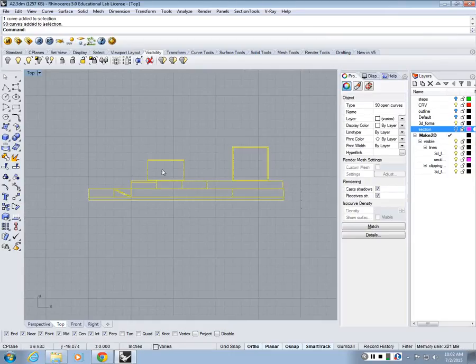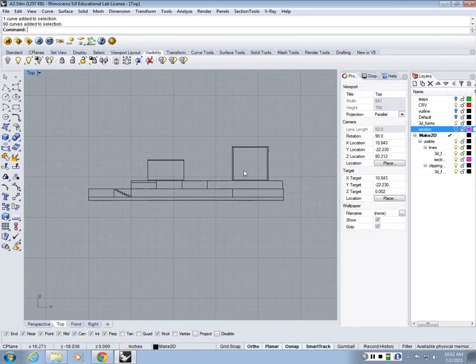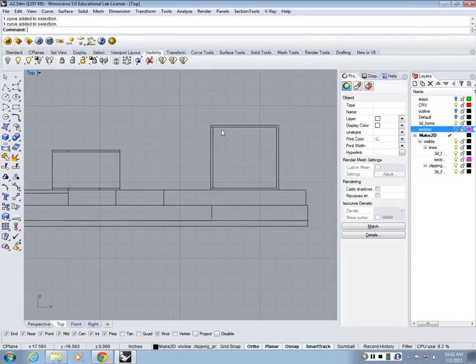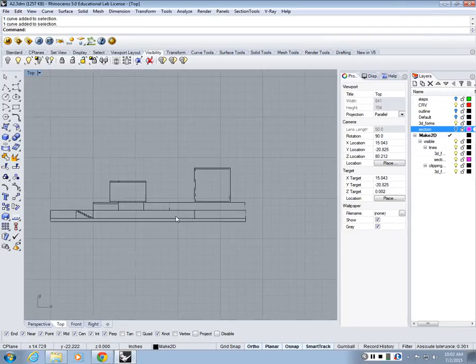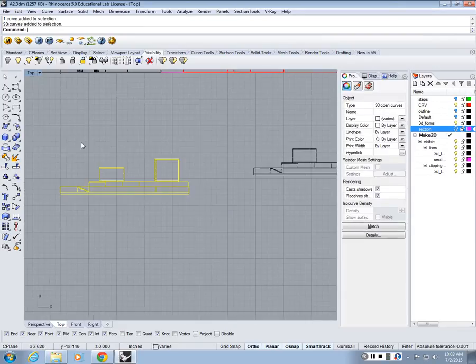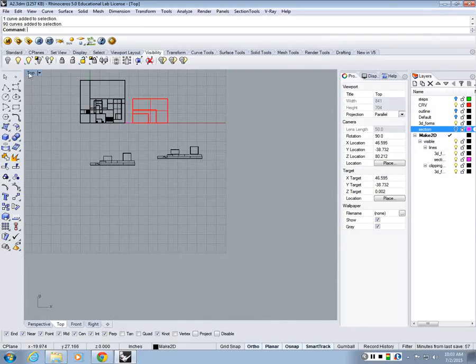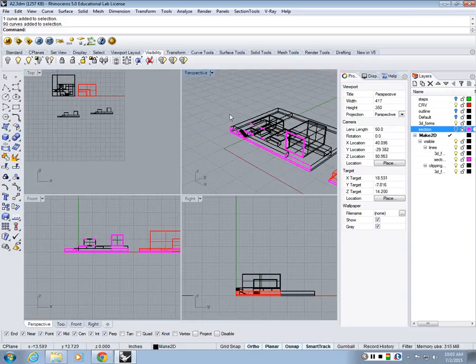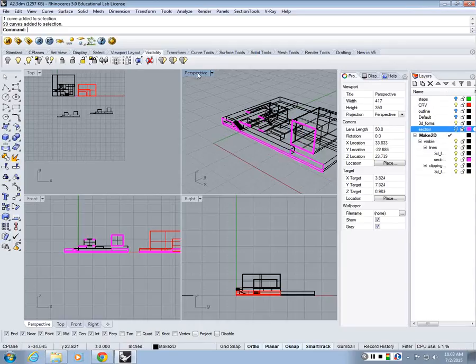I mean, this would be the most precise way of doing it. Sometimes it cuts the geometry, but it won't tell you what is cut and what isn't, right? And that's why when you make 2D, it's best to get a perfect section outlined on a different layer so that you can edit it for Poché elements. Okay?